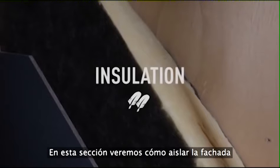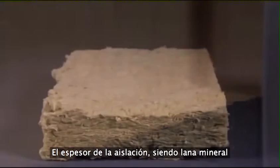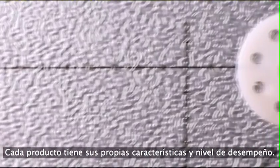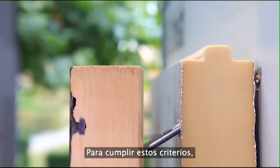Insulation. In this section, we will look at how to insulate the facade and prevent thermal bridges. How to insulate the facade. The insulation, be it a mineral wool or a foam-based material, must be thick enough to suit the building's function. Each product has its own characteristics and level of performance. Ideally, the insulation should be fireproof, water-resistant, and breathable. To meet these criteria, a number of insulation suppliers have a board for ventilated facades.